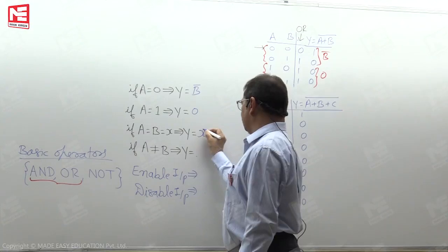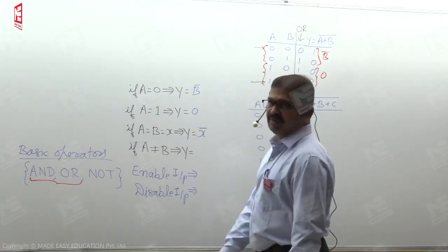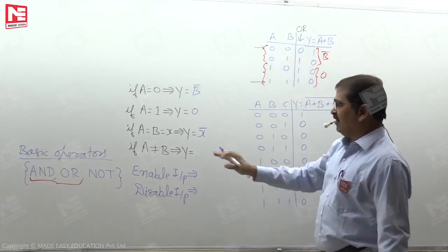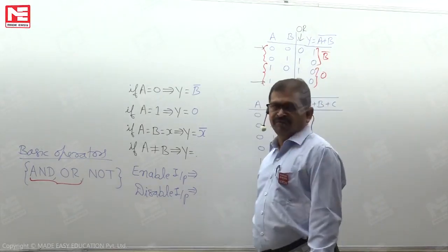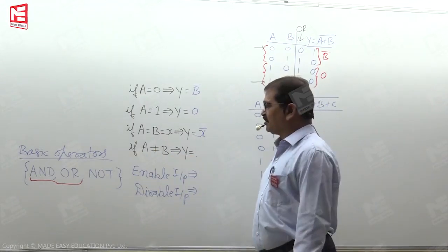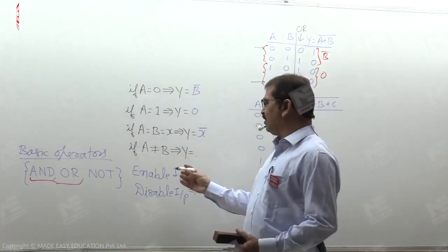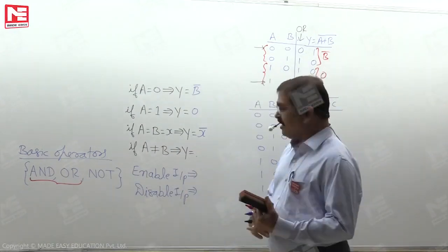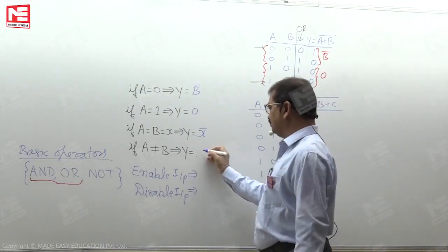So if the input is x, then it is the complement of x. Whenever both the inputs are not connected to the same Boolean variable, it is possible to look at one of the variables as guaranteed 1. Whenever one of the variables is guaranteed as a 1, then the output must be 0.